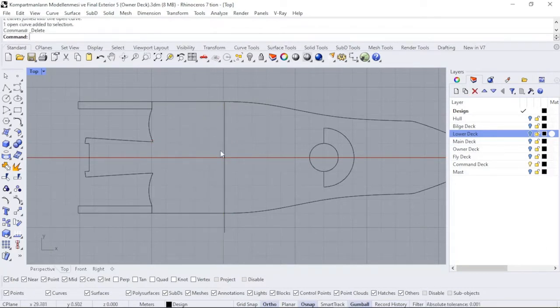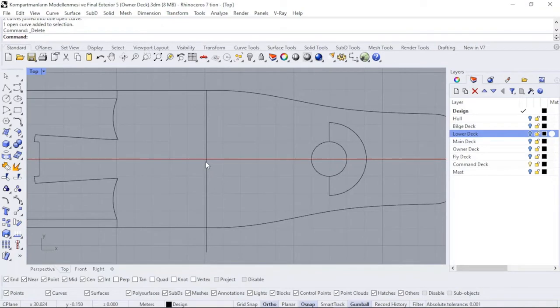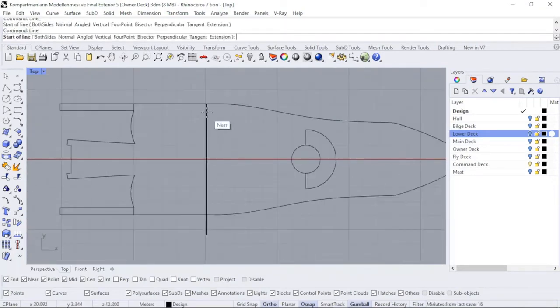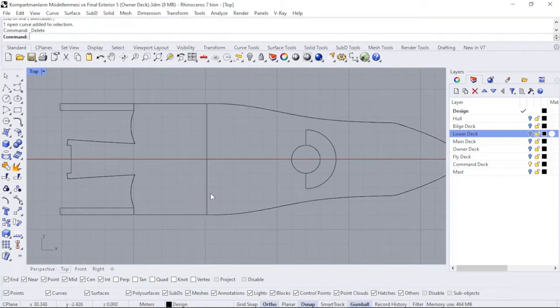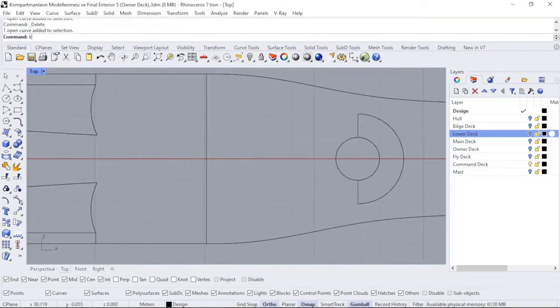There will be a saloon at the stern and we also add a table here for the meeting. We would have a room like half office, half living room here. Next, I want to add a door here, line. I draw another straight line holding end and intersection. I re-enter the line command and holding from the mid, I draw a 0.7 meter long line upwards.